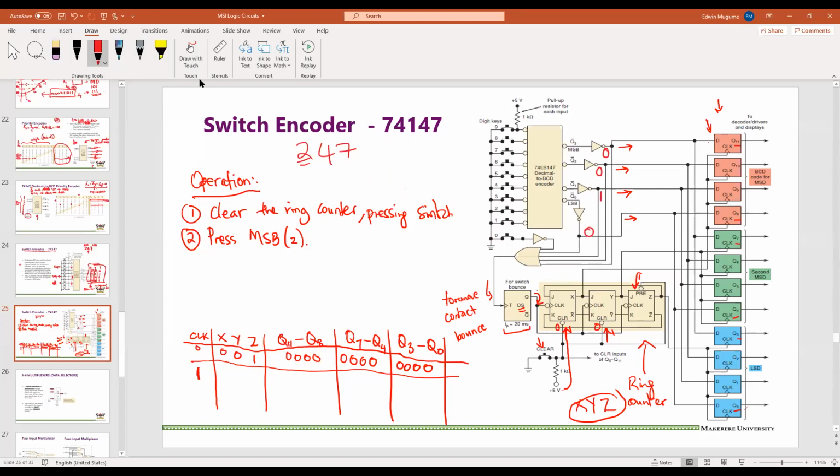And you can see these are going into the OR gate here. Because there is a 1, all of these inputs, 0, 0, 1, 0, are going into the OR gate, but one of them is a 1. That means that I'm going to have an output 1. When I have an output 1 going in here, my Q will go high.